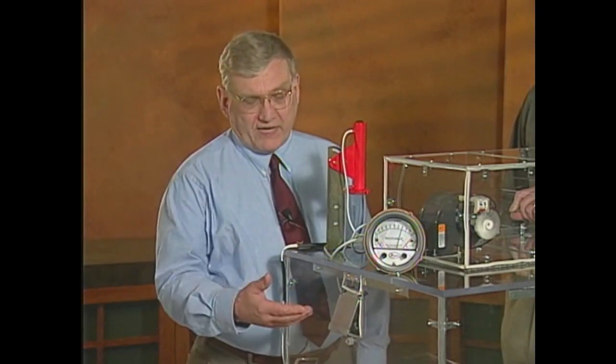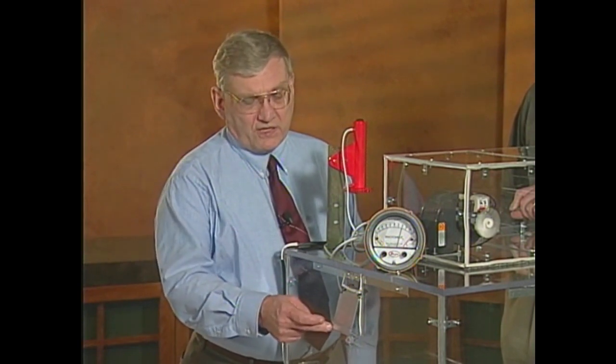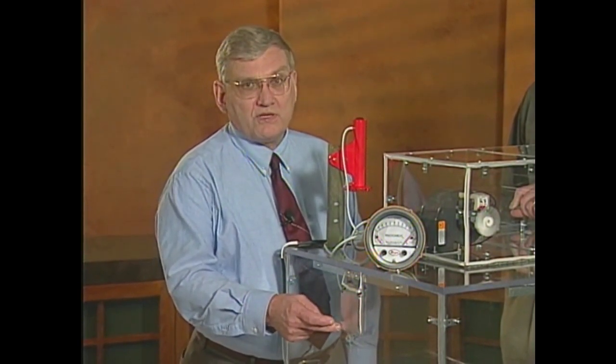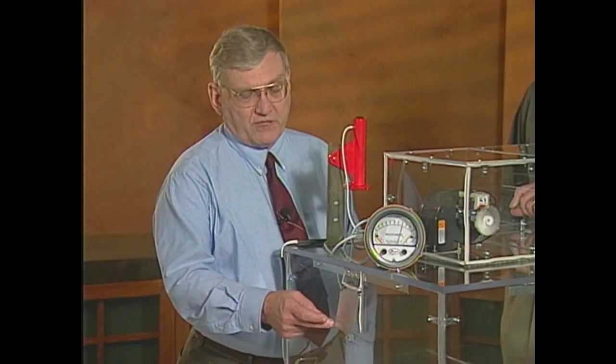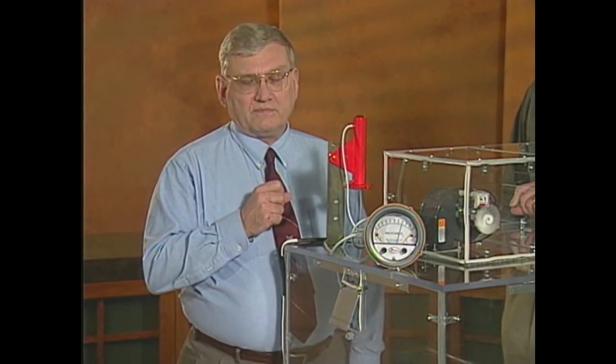Barometric damper location is very important in the building. You can see in our example here that if you place it on the side of the building where the wind is going to be impacting, and maybe the prevailing winds are coming from this direction and they hit the barometric damper, they're going to have a tendency to close it. If they start to blow it closed, you're going to start seeing the static pressure in the building going up. Consider locating barometric dampers on the various faces of the building.